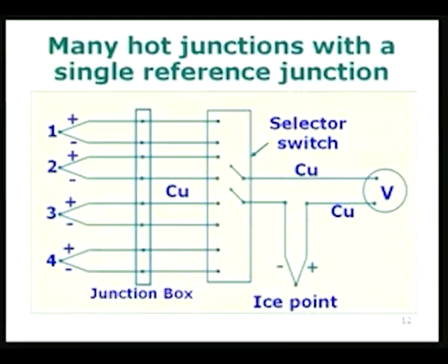The question is, can we confine it to a region close to the junction, and that is in fact what is going to happen in practice, because the wires are very thin and usually they are very long, and because they are very long, they are going to be in the laboratory space, and the laboratory space is a uniform temperature. Therefore, it will cool to that temperature, and confining the temperature variation to close to the junction is an automatic phenomenon which takes place, and therefore, we are able to practice thermoelectric thermometry by using an arrangement which is shown in the figure.